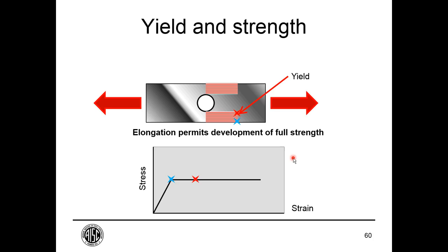Our stress can be fairly high there too. And so when you integrate that stress across this portion of the section, you get a higher force. So we're utilizing this material more because it's more ductile. So ductility isn't just displacement capacity, it builds up into extra strength as well.